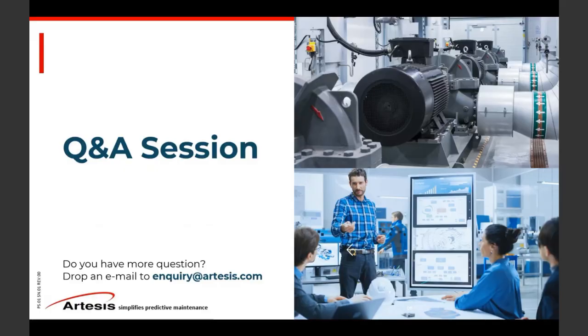There's another question. Which technology inputs is your software working on? Only vibration analysis or anything else? I thought I pretty much covered this already. We don't use vibration. Our system is sensorless. We're using only electrical signals, voltage and current, and we turn the motor itself into a sensor, where it gives you all your vibration information, or electrical and process and pump performance monitoring. That's why at the end, I mentioned the beauty of our system is that it's capable of capturing all this information from different disciplines, which you would normally use different tools to detect.